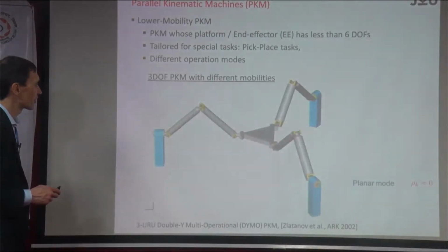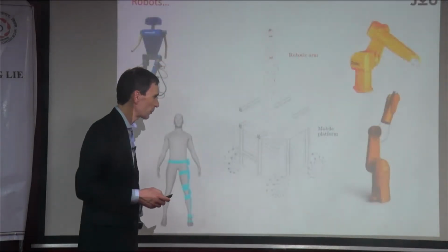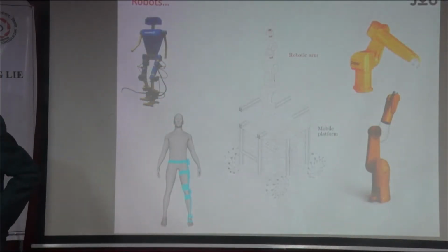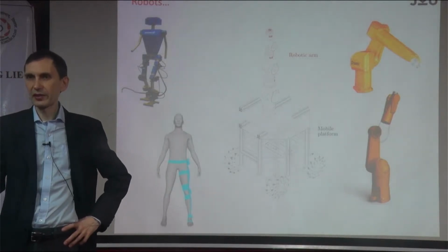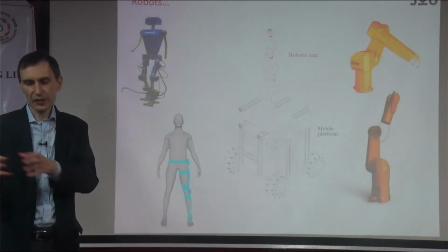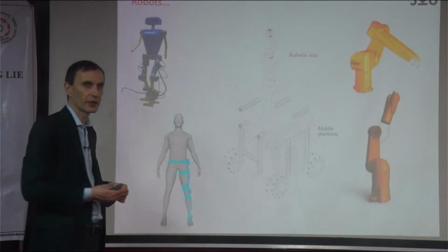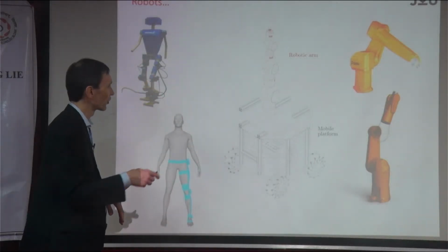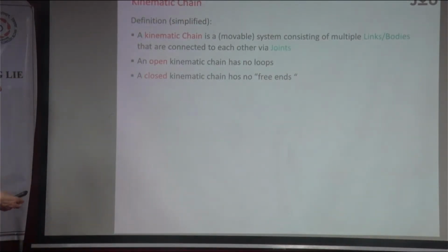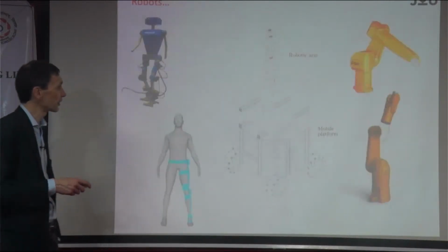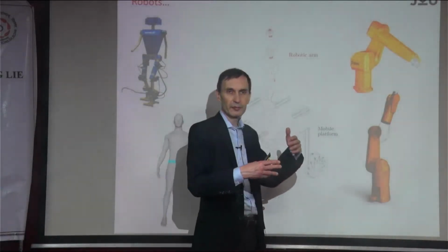Okay, and I think now we should maybe get to some more details. We talked about loops and not loops, and joints and where the joints are. At the beginning, you mentioned so many joints, so many links, but what about the geometry? We really have to separate things. First of all, look at the topology, and then see what particular geometry we are going to give the mechanism. If you look at all these mechanisms, there are different topologies. Just for completeness, we need a bit of terminology. If you look at these systems, you can always talk of what we call kinematic chains.